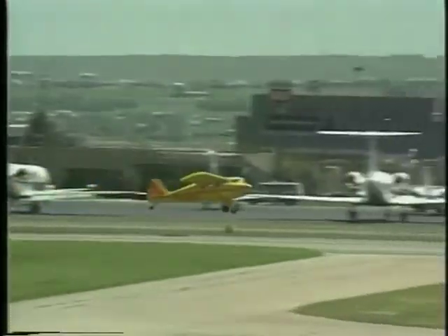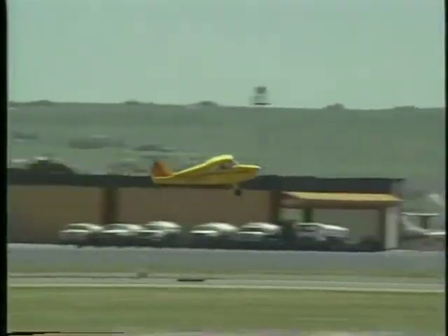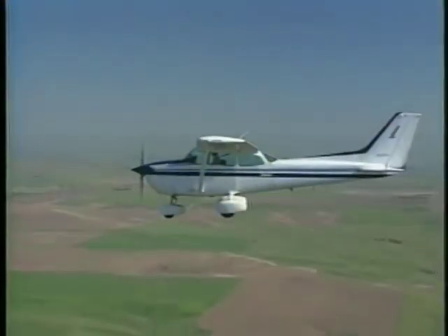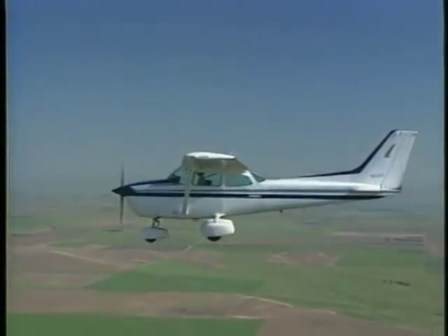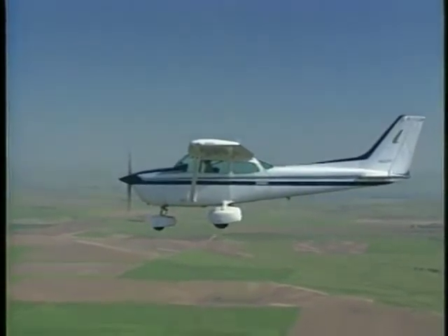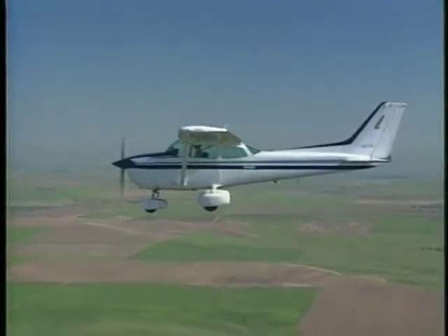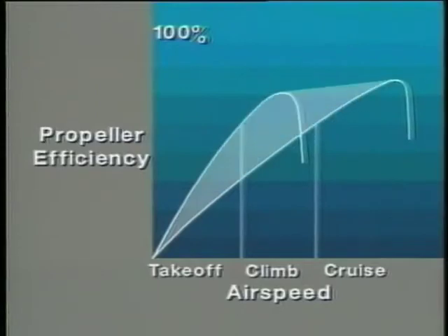Fixed-pitch propellers can be designed either with low blade angles to produce optimum takeoff and climb performance, with high blade angles for optimum cruise performance and fuel economy, or as a compromise between the two. On aircraft equipped with constant speed propellers, the propeller can be adjusted to maintain the optimum pitch angle. Thus, constant speed propellers can maintain a high level of efficiency over a wide range of airspeeds.